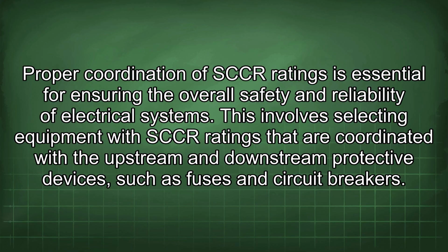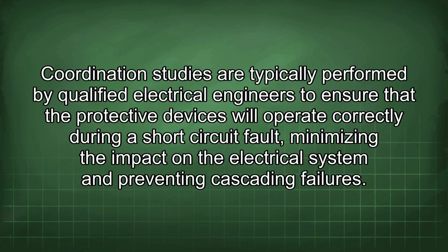This involves selecting equipment with SCCR ratings that are coordinated with the upstream and downstream protective devices such as fuses and circuit breakers. Coordination studies are typically performed by qualified electrical engineers to ensure that the protective devices will operate correctly during a short-circuit fault, minimizing the impact on the electrical system and preventing cascading failures.